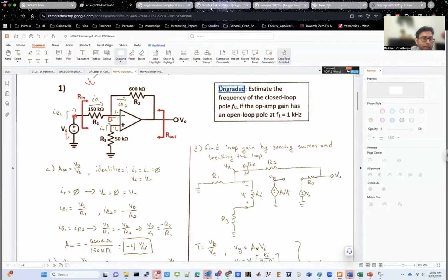It cannot be anything else because of Ohm's law, because the left side of the resistance R1 is VT, the right side of the resistance R1 is forced to 0 volt because of the virtual ground property. And because of that forcing, the current is forced to be VT over R1. So that's basically the current I flowing through the R1 resistance.